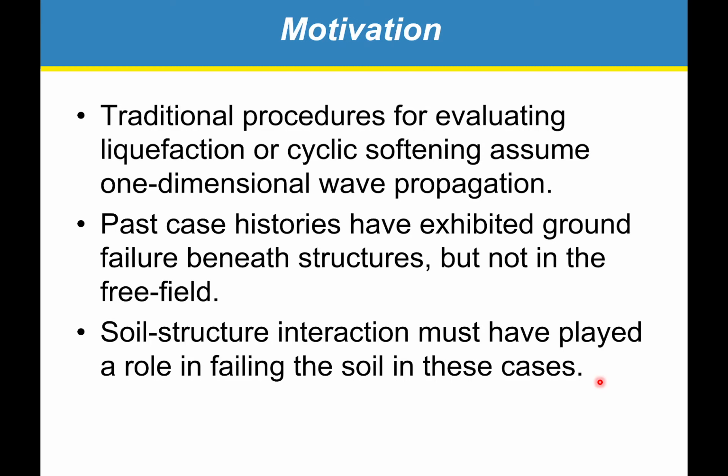That's something I forgot to mention when I showed that building that tipped in Adapazari. There were silt boils and signs of ground failure beneath that structure and in the vicinity of the structure. But if you went away from the structure to the free field, there were no signs of ground failure. So that's evidence that soil structure interaction played a role in that failure, and that if you just did a free field analysis, you would underpredict the potential for ground failure.